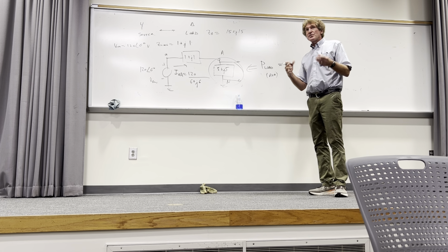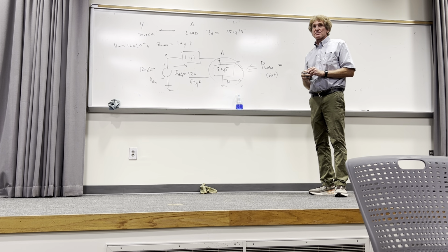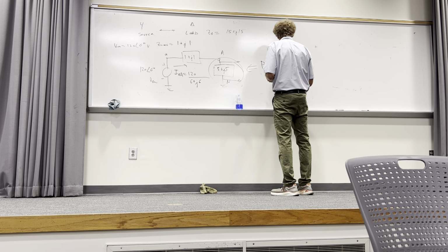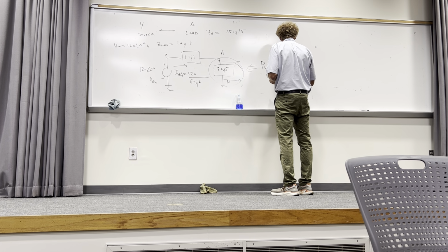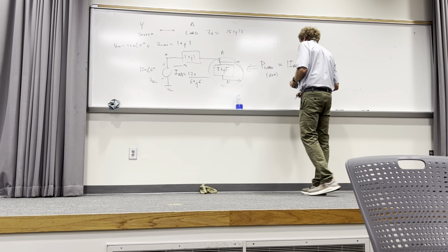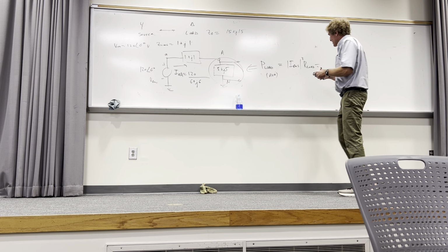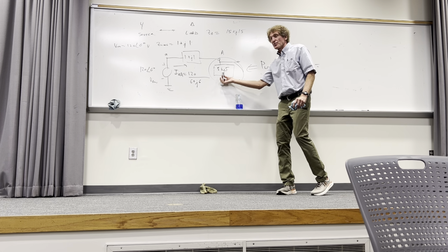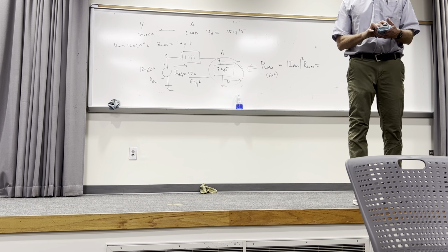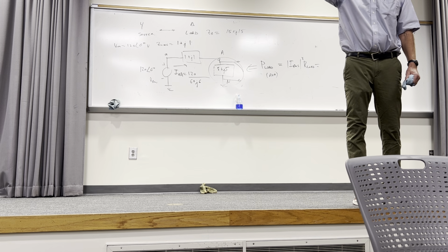The way I would do it, this is average power, not complex power. The way hopefully you would do it would be to realize the only thing that matters is the magnitude of IRMS squared times the resistance, R load. So R load there, just the resistive part, or the real part. It would only be 5 times IRMS squared. How many understand that? That's it.